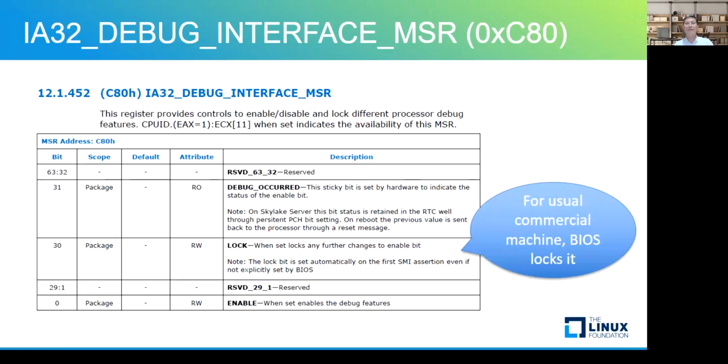I have to mention that to do DCI debugging, we usually need a customized BIOS. The reason is for security concerns. Intel advises our OEMs to turn off the feature in BIOS.